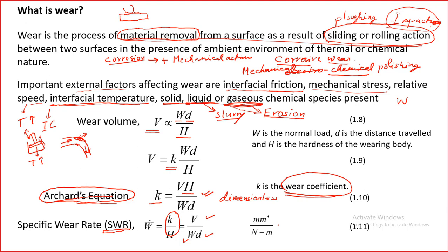Also remember that the units of specific wear rate are millimeter cube over Newton meter. It's not proper to use meter cube, even though dimensionally it doesn't make any difference, but in a practical sense, because we always compare one thing to another, the units also should be the same. So this is the proper unit for specific wear rate.